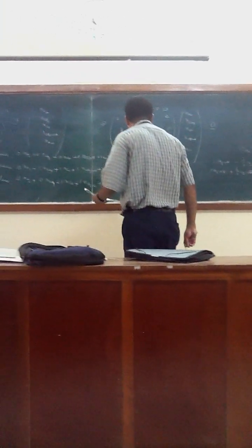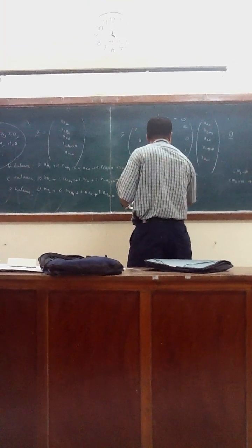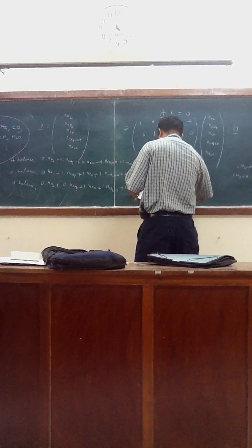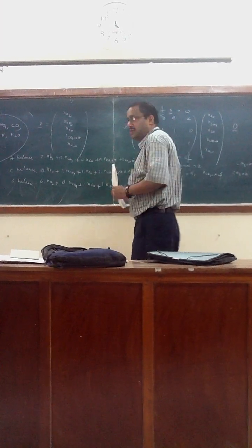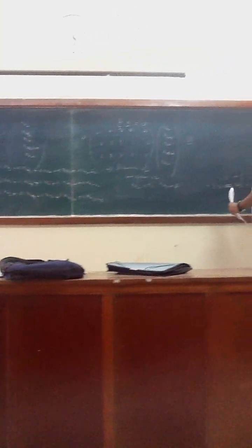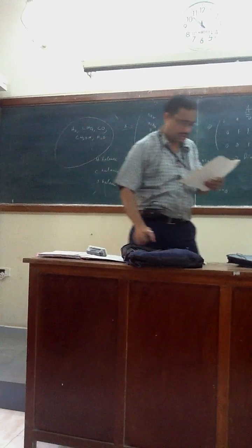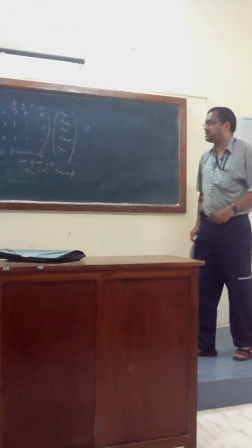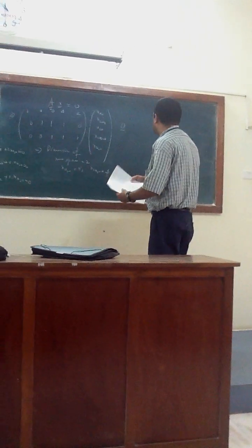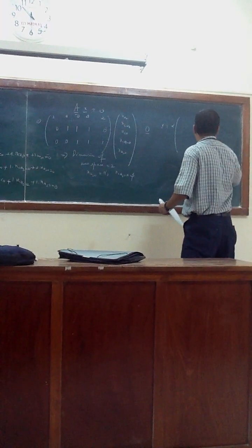So we have 5 unknowns and 3 equations. So NH2O you will write as alpha and NCH3OH you write as beta. That is the way you check the null space, right? That is the way you do null space. NH2O equals alpha and NCH3OH equals beta. Right? So your job is to give me the answer of X vector in terms of null space. Alpha I want plus beta I want.